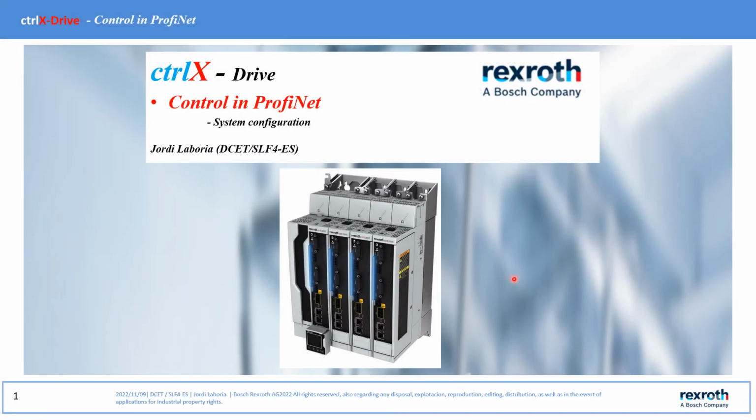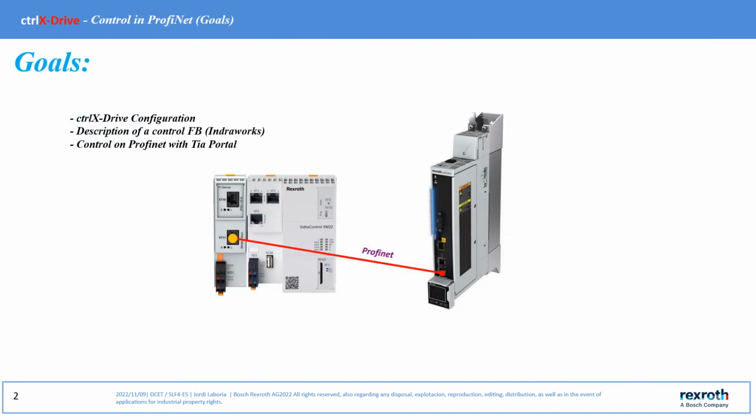Hello everybody! In this new tutorial we are going to explain how to configure a ctrlXDrive to work in ProfiNet. In this document we will see the generic configuration and some differences with respect to the previous use of Indraworks in ProfiNet. In the manual we will also see the operation of the FB that I have prepared for the activation and status of the ctrlXDrive.